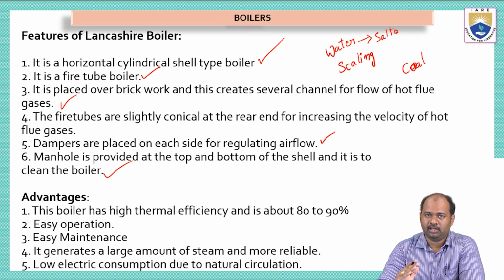This has to be cleaned, otherwise it may lead to corrosion of the boiler structure. Because we are talking about steam, when the water is inside the water tank and is boiled, steam will be separated and these salts will be formed as a layer on the surface. This process is called scaling, and this scaling has to be removed. That is why the boiler structures are provided with manholes, where a person can go inside and remove the scales that are present on the surface of the boiler.